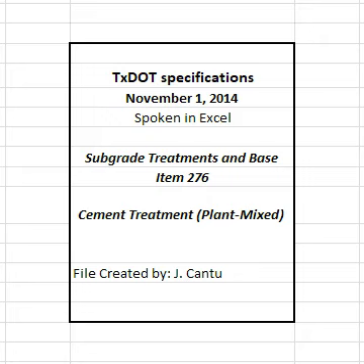The engineer will determine the moisture content in the material in accordance with Tex-103-E from samples taken at the time of weighing. When material is measured in trucks, the weight of the material will be determined on certified scales, or the contractor must provide a set of standard platform truck scales at an approved location. Scales must conform to the requirements of Item 520, Weighing and Measuring Equipment.